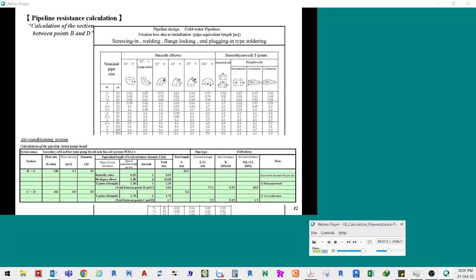The pipe size at the first branch is not changed, so refer to the not narrowed column in the straight flow category. The equivalent length is 1.3 meters. The size of one side of the T-joint is different from that of the other side of it across the branch point. Confirm diameters to determine the equivalent length.